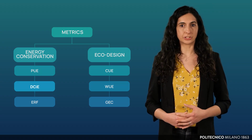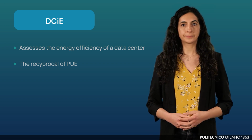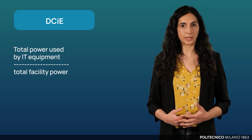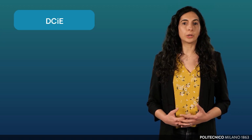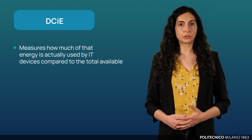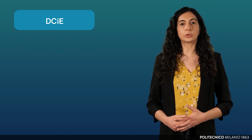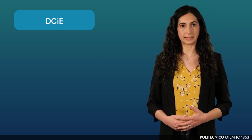Let's now briefly discuss the metrics mentioned to understand their meaning. Data center infrastructure energy efficiency is used to assess the energy efficiency of a data center and is the reciprocal of PUE. This metric is calculated by dividing the power used by IT equipment by the total energy consumption of the facility. While PUE helps organizations understand how efficiently a data center uses incoming energy, DCE measures how much of that energy is actually used by IT devices compared to the total available. This metric is usually expressed as a percentage. The higher its value, the greater the energy efficiency of the data center.